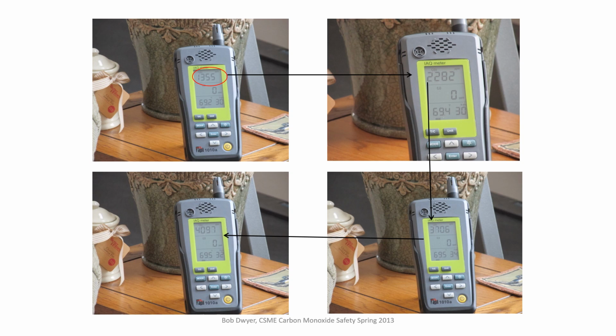When you have this kind of test instrument, yeah, I sound a little bit geeky, but if you want to take a look at office buildings or gatherings or classrooms, that's the best place to take your CO2 test instruments. There are a lot of complaints about uncomfortable situations with air quality in office buildings. Too hot, too cold, it's stuffy, I'm falling asleep. People buy energy drinks when it could be just as simple as too much CO2 in the space. Let's measure CO2, carbon dioxide.